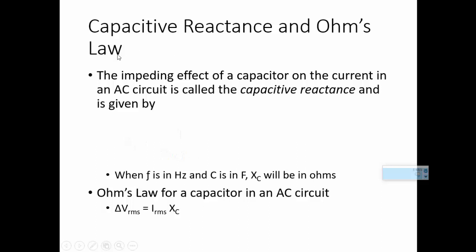Now, there are some terminologies that you need to begin to understand. The capacitor is measured in farads, and we'll talk about this in detail when we look at some sample examples. But you need to understand that there is what we call the capacitive reactance. When we want to apply Ohm's law in relation to the capacitor, we're not taking its value in farads. We're supposed to look at what we call the reactance of the capacitor. The reactance of the capacitor is like the resistance of the capacitor, and I'm going to talk about that.